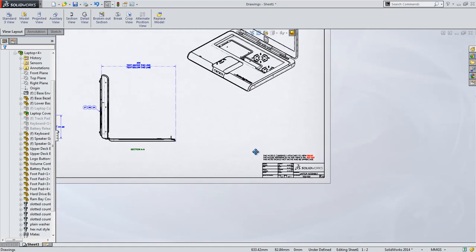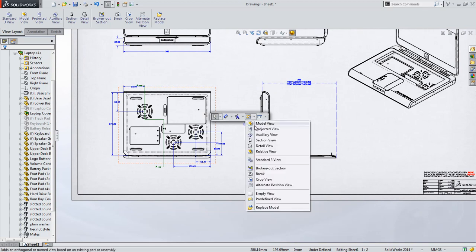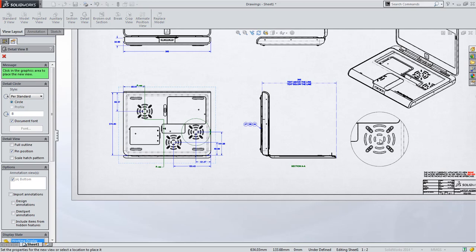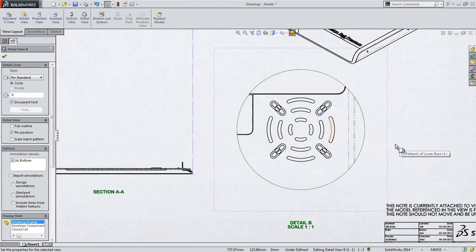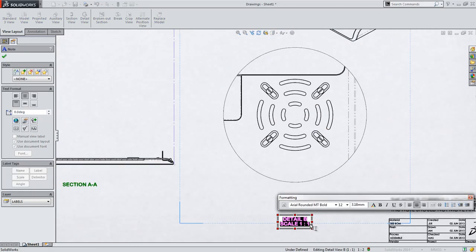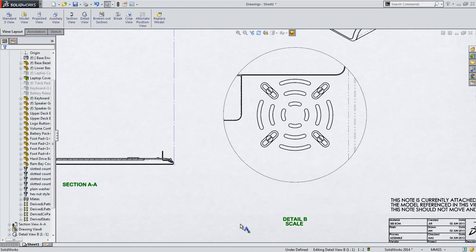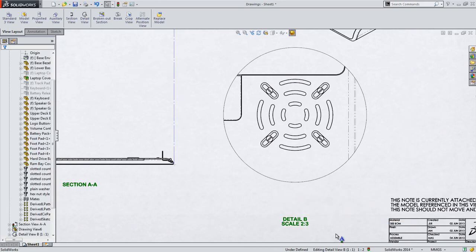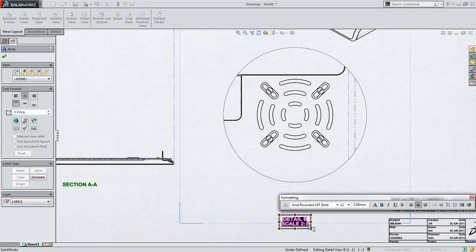A detail view will provide us with an opportunity to look at the next set of enhancements in closer detail. When detail views are created, the note for the view is provided automatically. These notes come with intelligence built into them. However, in the past, if you deleted this text, the intelligence would be lost. In fact, if you deleted all the text, how would you get it back? Now with view tags, this information can be propagated automatically using special tags which reference the drafting standard in use.